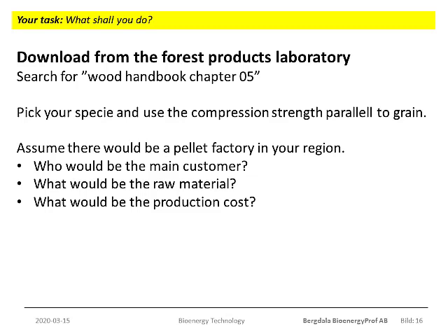So what you have to do to be able to make an estimate is first to get proper data for the wood species that might be used. To find such data, I would recommend you go to the web page of the American Forest Products Laboratory. You will find the link among the external links with this nugget. Then search for the Wood Handbook, Chapter 5, and look in tables 5.3, 5.4 and 5.5. As you will see, these tables are fairly comprehensive, and chances are that you might find the species you are looking for in these tables. So the value for sigma sub 0 can be read from these tables.